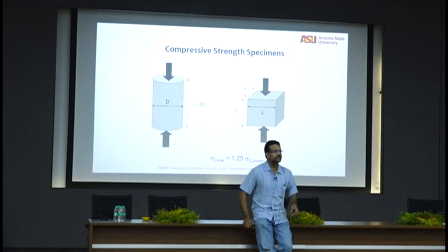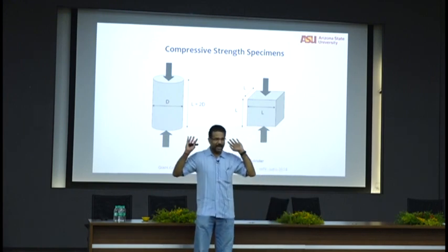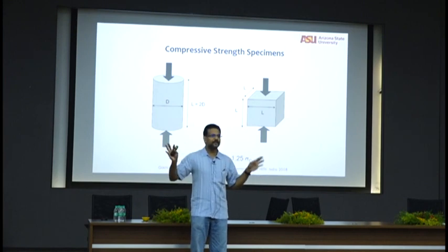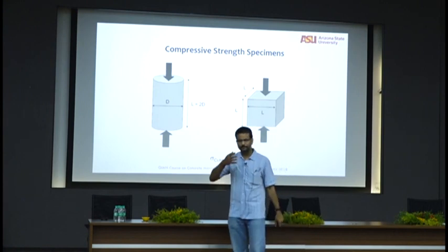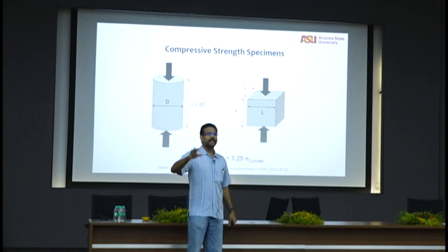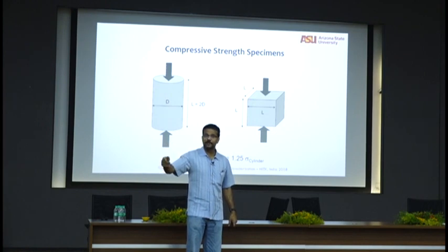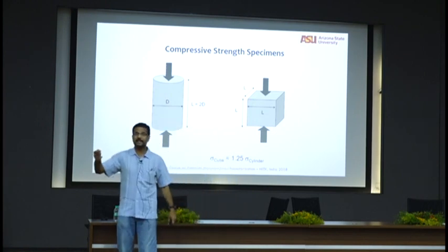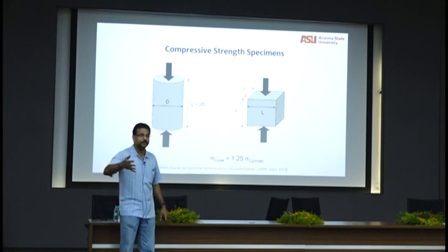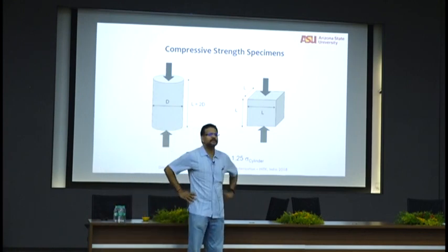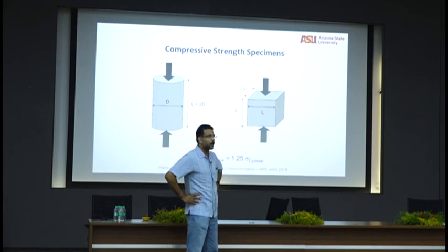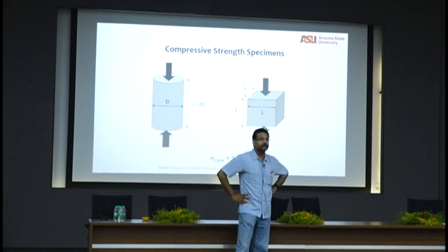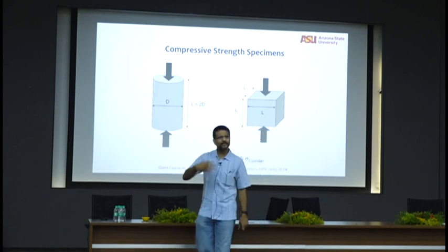Your maximum usable compressive strain in concrete is 0.003, that doesn't change. You come up with whatever kind of concrete for regular construction, that doesn't change. Ultra high performance concrete, of course, you have to come up with your own standards. It changes for shear, it changes for development length and anchorage, because reinforcement guys are coming up with better and newer rebars and more effective reinforcement. So the anchorage and development length changes quite a bit, and then specifications for columns under biaxial loading. That changes quite a bit because there's a lot of work happening on confinement effects in columns under biaxial bending, so you can get a more optimized design. Things keep changing every 3 years.